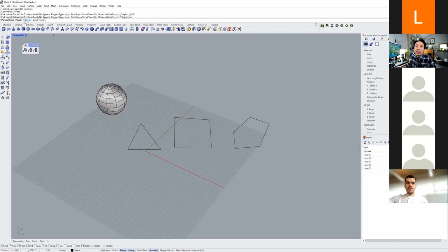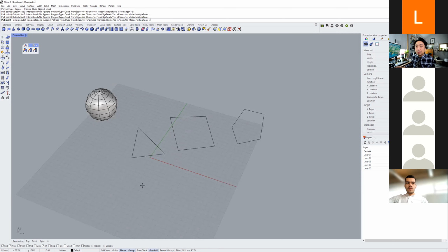So you want to click on it. You don't want it to be triangles. You want it to be quads. Quads have a huge advantage because, like in a NURBS surface, quads means you have 2 axes that you can deal with: an x-axis and a y-axis. Having that makes a huge difference. So let's just go with quads always. From edge, yes. I will show the difference. With the rest of the parameters, you can probably forget it. Now we can start building shapes. Literally, you are just drawing.